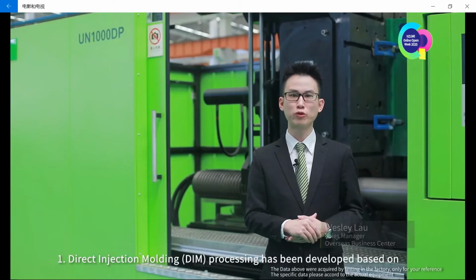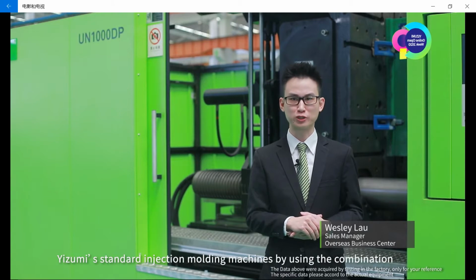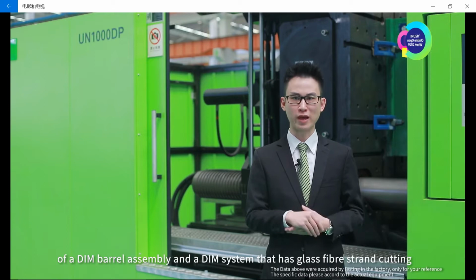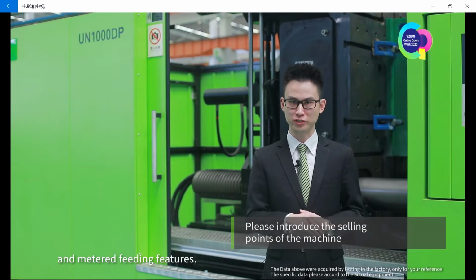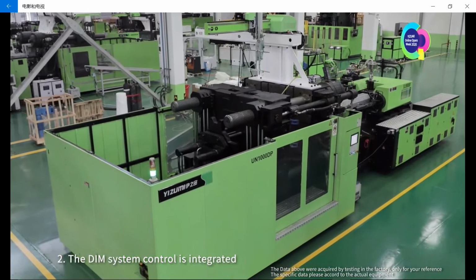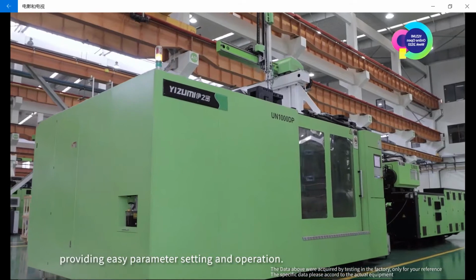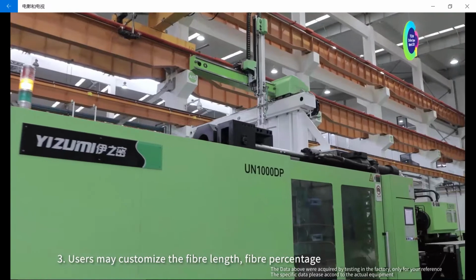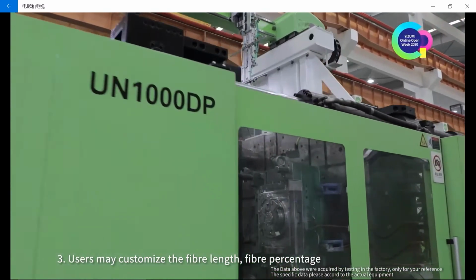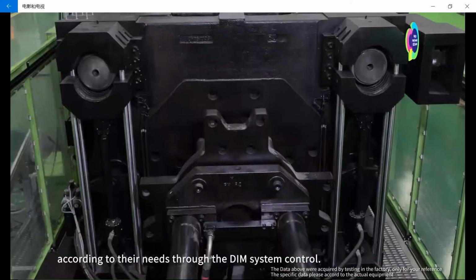Direct injection molding processing has been developed based on Izumi's standard injection molding machines by using a combination of a DIM barrel assembly and a DIM system that has glass fiber strand cutting and metered feeding features. The DIM system control is integrated in the injection molding machine controller, providing easy parameter settings and operations. Users may customize the fiber length, fiber percentage, and material combinations according to their needs through the DIM system control.